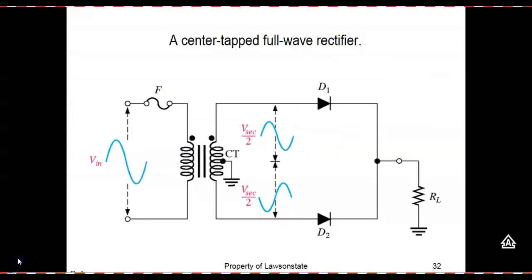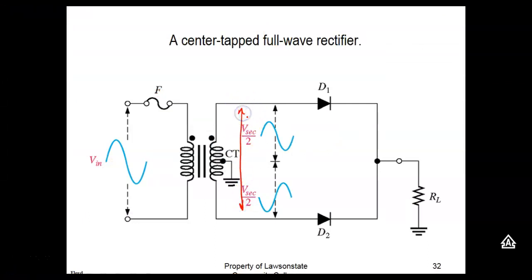What they do is use the entire secondary of the transformer, and that's the way it's rated. And we're only using 1/2 of it at a time. So I could say my volts DC would be equal to approximately 6.3 times 0.9. That's the easiest way to do it. And what do we come up and get? So as soon as you got 11 volts, I knew exactly what you did.